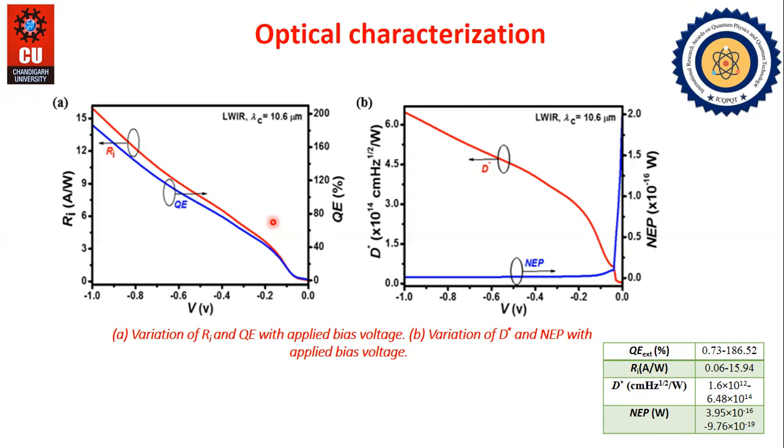Under the hot carrier multiplication effect, numerous carriers are generated from a single incident photon in the bilayer graphene, or we can say a single incident photon will excite one valence band electron to the conduction band, which further stimulates the other valence band electrons to move to the conduction band. Such an inverse non-radiative Auger recombination process, which is known as the impact ionization process in the bilayer graphene, results in the hot carrier multiplication effect.